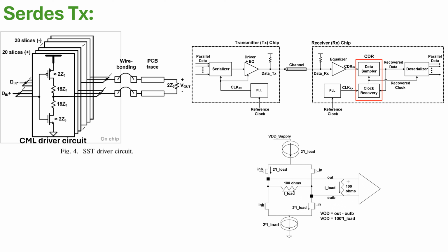The second one is very similar to LVDS, where we have a termination at the receiver end too, and a differential logic, low voltage differential signaling, where the output differential signal is limited to a maximum of 400 millivolts with an output common mode of 1.2 volts, and it depends, maybe in different technologies different things. So LVDS can be used as a driver or transmitter in the SerDes.